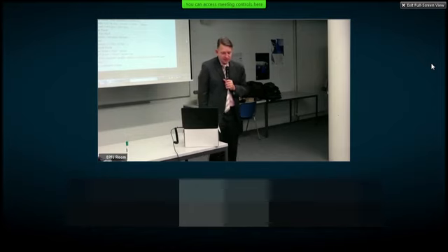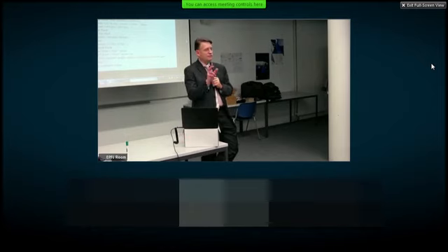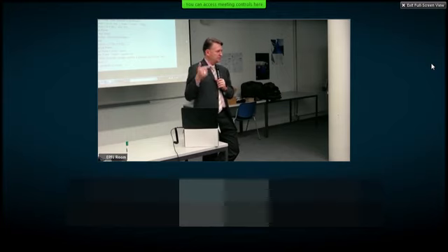Thermal flux is essentially heat flux, dQ/dt. There are three fundamental mechanisms of heat transfer, right? Conduction, convection, and radiation. In spacecraft, radiation is probably the most important because that's the only way to get rid of heat out of your spacecraft. And then you can do conduction and convection internally.